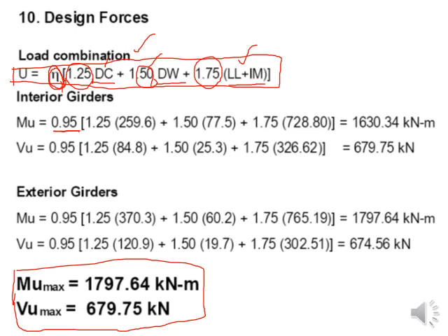Okay, wind loading, earthquake loading, and like this. So you have to be considerate, although the specific and separate design is always there. But at the first stage you need to incorporate all of those variant loads into it. So those variant loads are going to be incorporated by using this mu factor. The rest are the factors 1.25 with DC, 1.50 with DW, and 1.75 with the live loads, considering the lane load plus the moving vehicular load, and multiplying it with the impact factor.